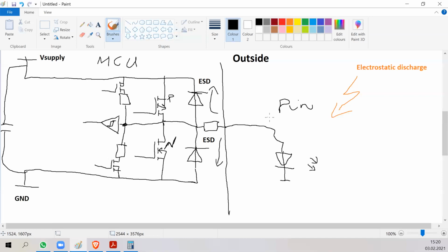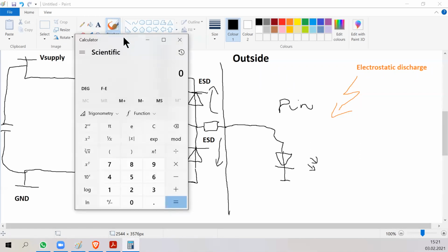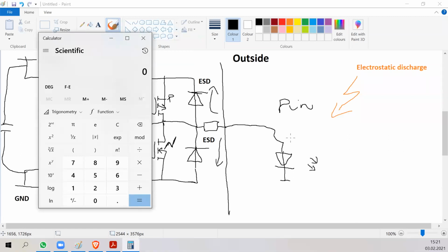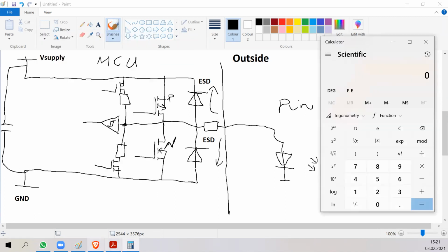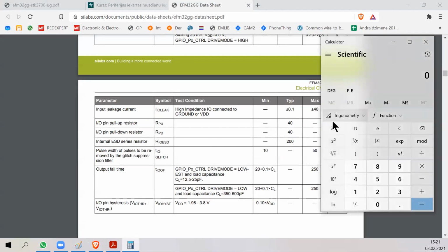And instead of putting it as output, high or low, you can just turn on or off the pull-up resistor. And this way, you don't need an external resistor for the LED. The only thing that you need to do is calculate what current will flow through this circuit. So if the pull-up resistor is 40 kilo ohms and it's short to the ground, then 3.3 volts divided by 40,000 is 82 microamps, which is a very small current, right?